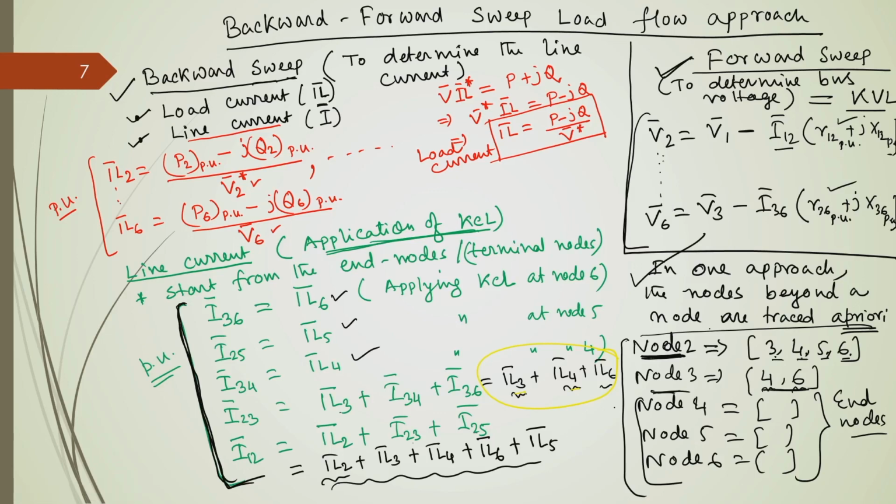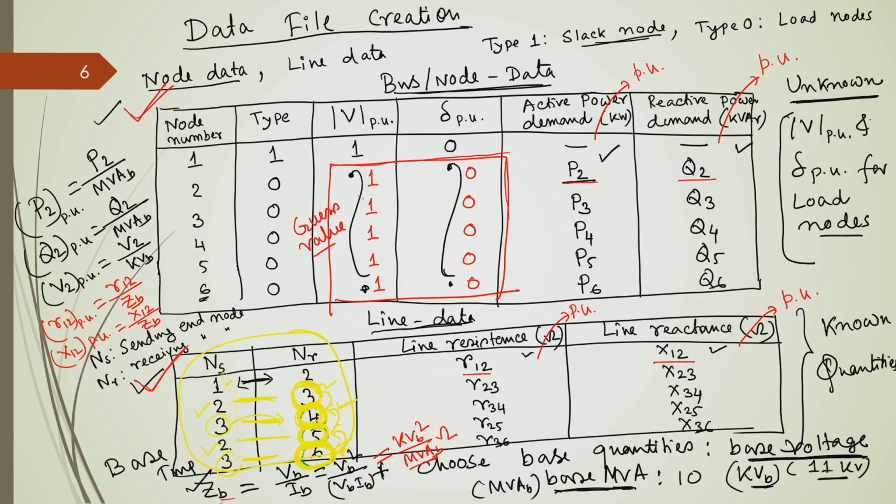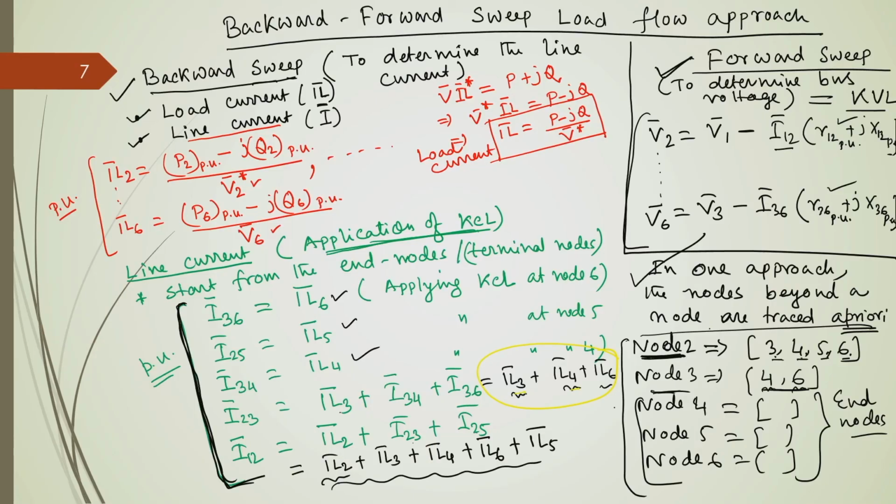And when we get these voltages we need to update the guess value. Okay. And we need to keep on updating till we get some converged value of these unknown voltages. Okay. So, here we will have some convergence criteria, which is normally the voltage error, the maximum error, and if we achieve this convergence criteria, we can say that the load flow is converged.